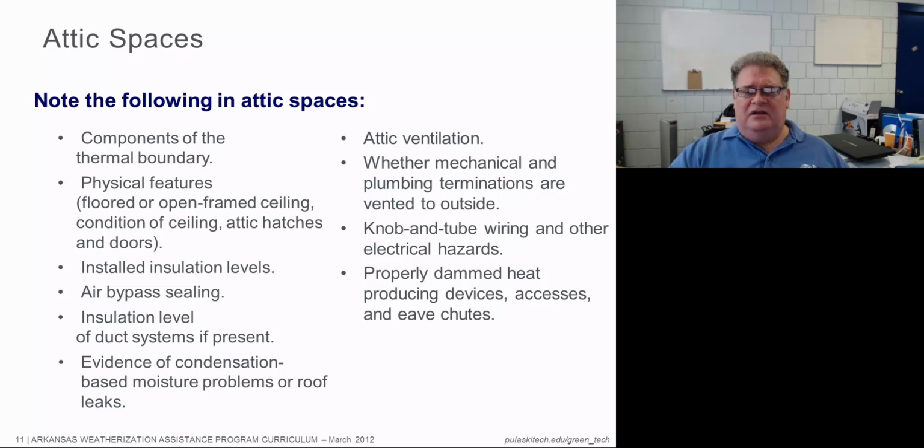Okay. Do we have heat sources that are properly dammed? Did we put insulation dams around all the type B vent and all the masonry chimneys, and bathroom ventilation fans that may have heaters, strip heaters built into them.